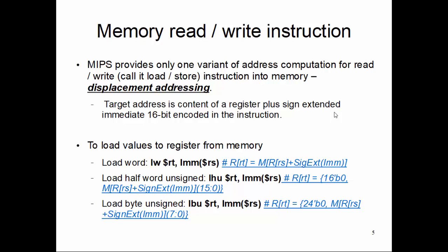The format for loading a value from memory to a register is this: LW stands for load word. Then you give a target register into which you are loading your value, which can be any register, S0, T0, etc. Then you give an immediate amount, which is the 16-bit offset value. And then you supply a base register name, which again can be any register. No one imposes any restriction on you not to use any of the registers.